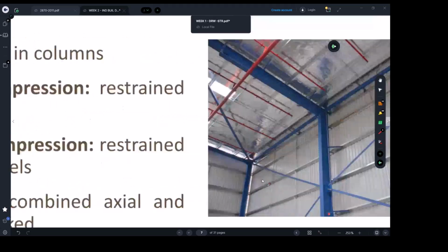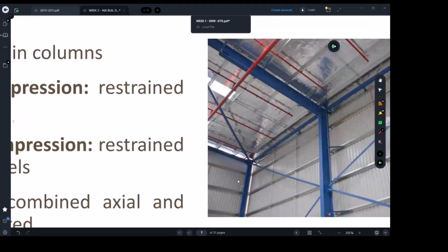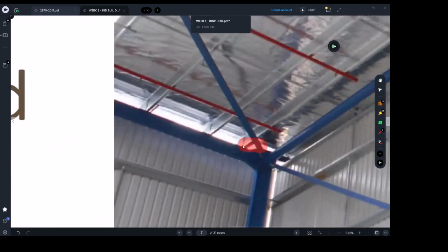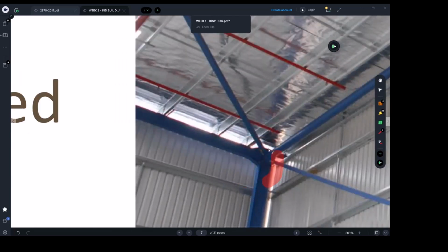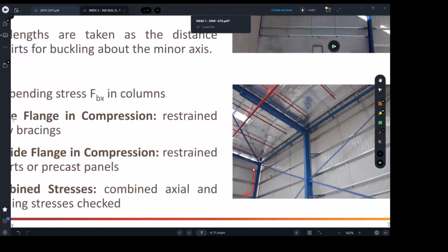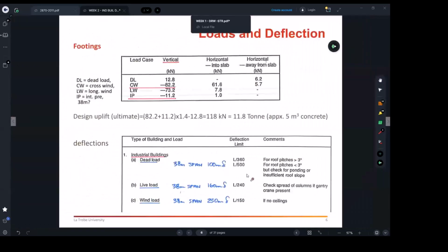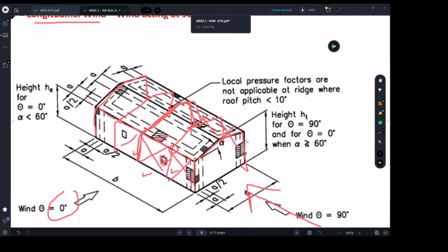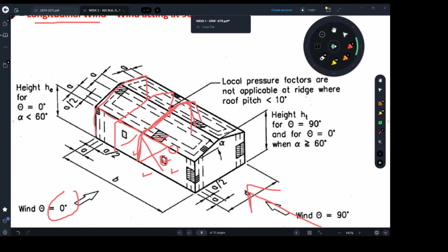That was the wall. Someone will say externally here we have walls. Yes, but the engineer seems to have decided here on still using portal frames. I can see this rigid connection. In some projects, like the one you're going to work on, the front ends are not portal frames. You're going to see that in your project, your assignment. So on the front side and the back side, you can decide not to have a portal frame. You may decide to simply have an X bracing, because you've got a wall to put the bracing in, right? You can have a simple beam to column connection and get it all done.